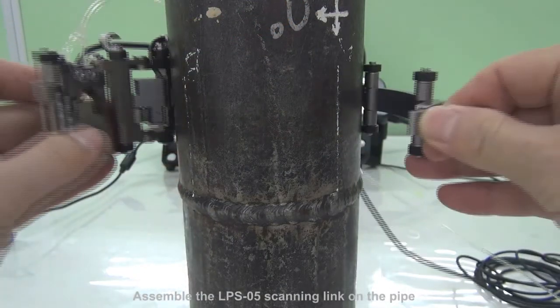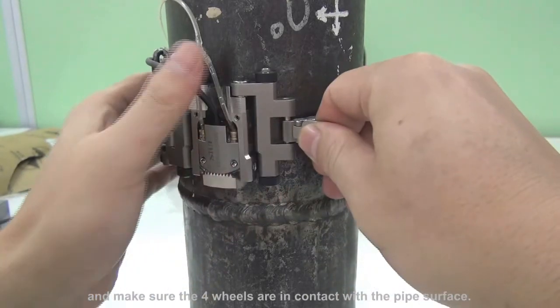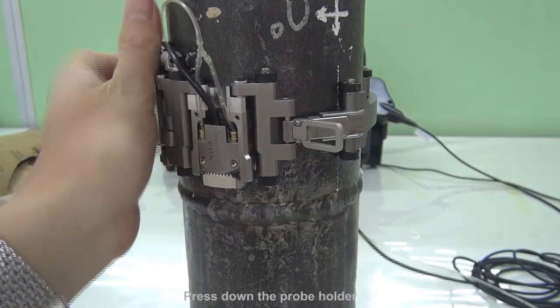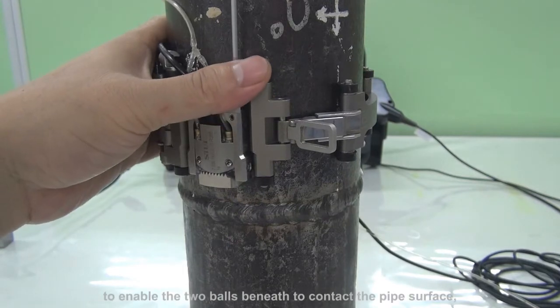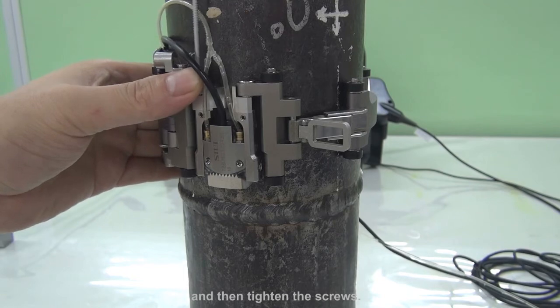Assemble the LPS-05 scanning link on the pipe and make sure the 4 wheels are in contact with the pipe surface. Press down the probe holder to enable the 2 bolts beneath to contact the pipe surface, and then tighten the screws.